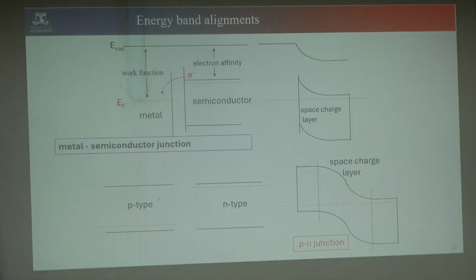And the same thing, if you compare, in N-type it will go down, in P-type it will go up, because on the other side we saw it is going up. So finally, this type of depletion region will form. This time we explain how the band bending is formed, because when you join metal and semiconductor together, there is a transfer of charge that will happen. A depletion region will form. The depletion region will make a space charge.